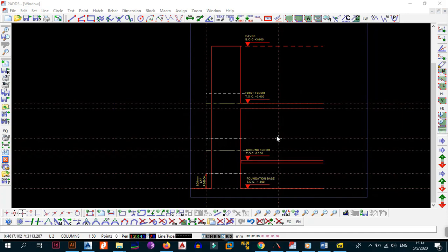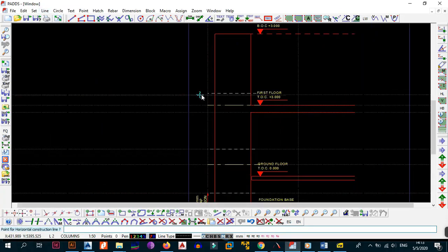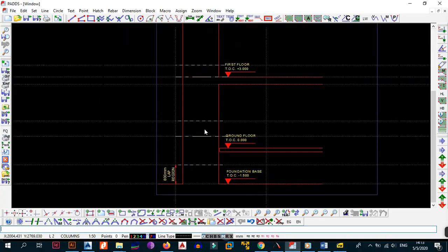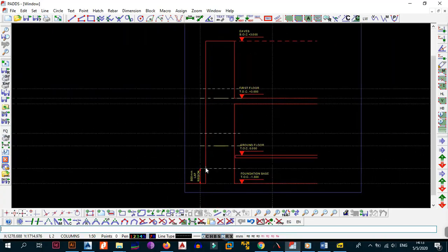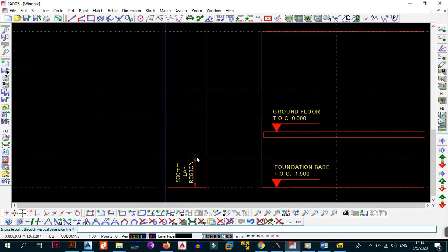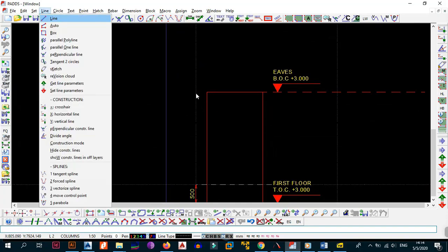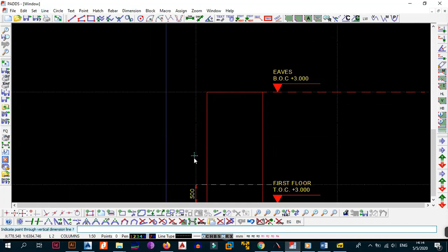So in this case, let's make sure that we have LX at every point. All right, let me put LX. Right, what's happening? LX. Okay, let's remove that line. It didn't go where I need it to be. In this case, I want it there. Now let's DV. So which is the best point to dimension? Well, in this case, you can do it DV from this point. It's just this one, then this point, then this point, and we didn't have a line there, so we're going to DV from this point to dimension vertically.